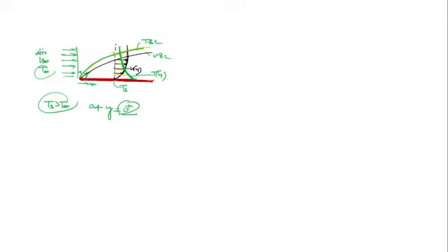In that case, when the fluid is stagnant, is the heat transfer through conduction or convection? In that layer, the energy gets transferred through conduction, so Q should be through conduction only. But as we move far away from the solid, you find that the fluid is in motion, and the velocity of the fluid increases. As you move away from the surface of the solid, the fluid is in motion.